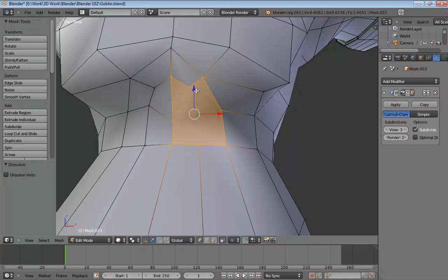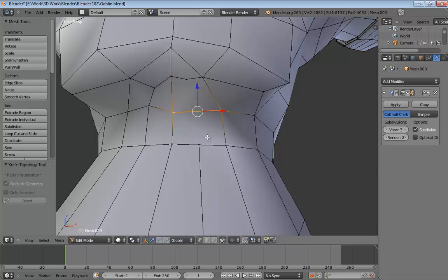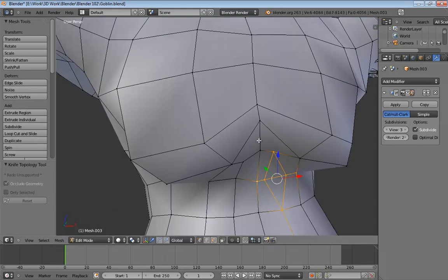But now we can switch over to vertices, and I can say, well, let's move this up here. And I want to split this in a very special way now. So I'm going to hit the knife tool, and we'll go from here to here. And then maybe get the knife tool again, and just split from here to here to here. And then one more knife tool split that goes from here to here. Maybe that's closer to what I actually wanted.